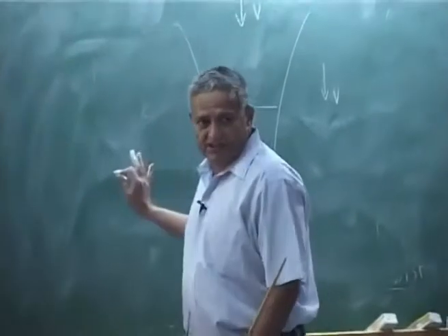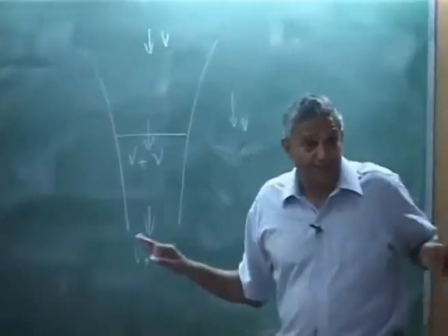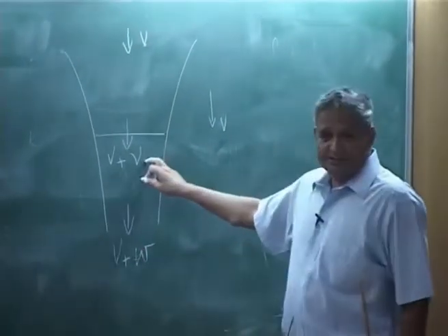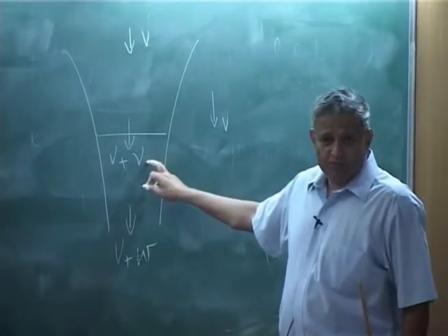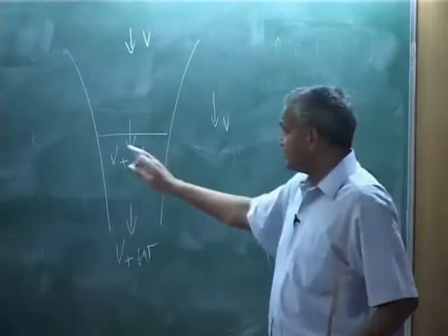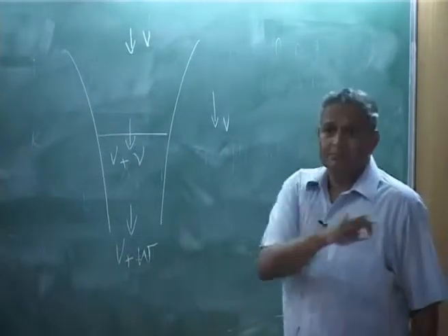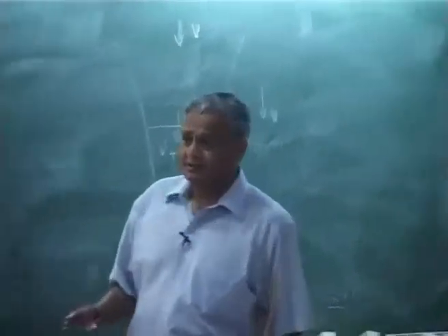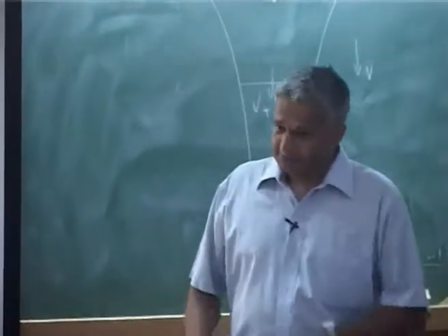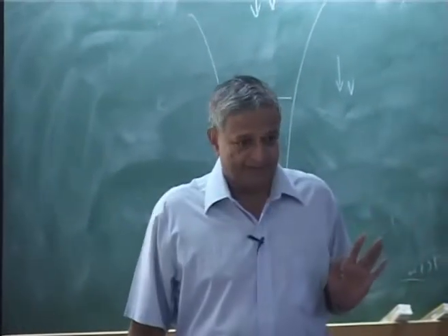But for this condition, I have made the assumption, please understand, that nu, the induced velocity, is constant and it is uniform over the rotor disc, it is uniform everywhere.